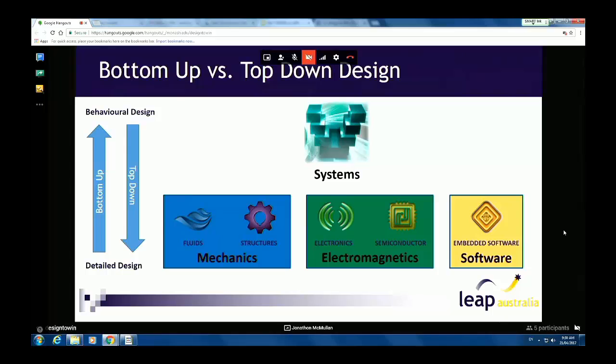So once you have a team of 50 engineers in it, and you need them each to be working as efficiently as possible, in much the same way that we develop software to scale on lots of cores, we need to develop a design process which scales with lots of engineers. So if we start at the top level, if we wanted to look at a hybrid car, we don't bother looking at how many poles the motor should have, but we work out roughly what voltage it should run on, how much power it needs to have to achieve our acceleration targets, what size the battery needs to be to run. And once we have ballpark figures for each one of those, we can start pushing information down from the top towards the detailed design phase to let everyone get started.